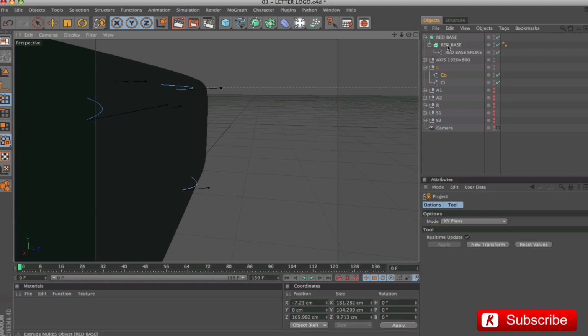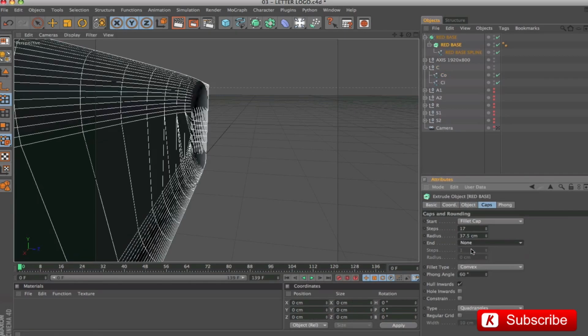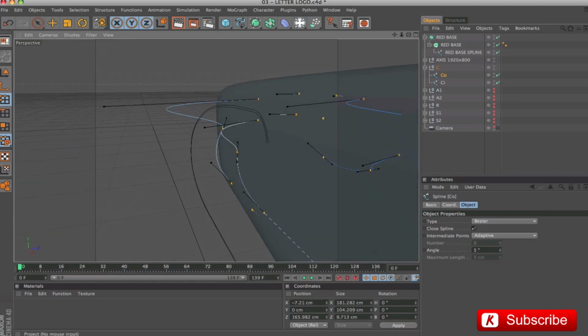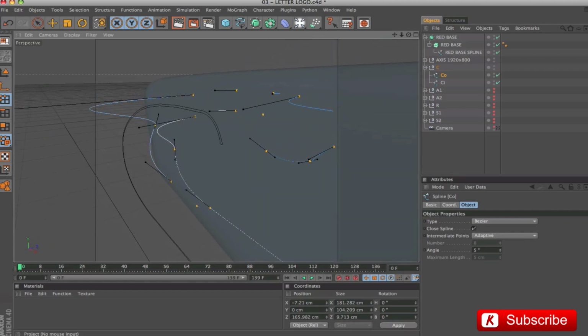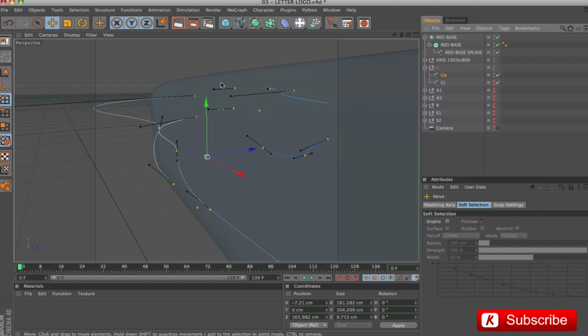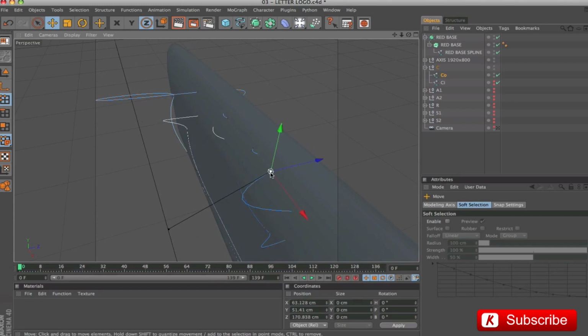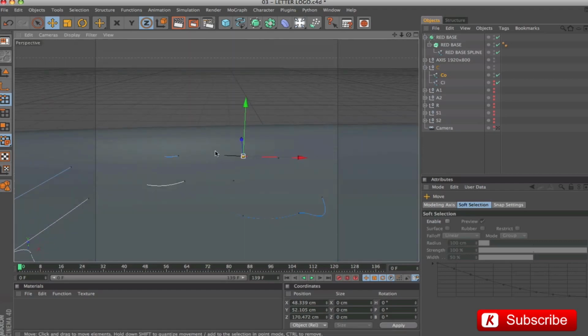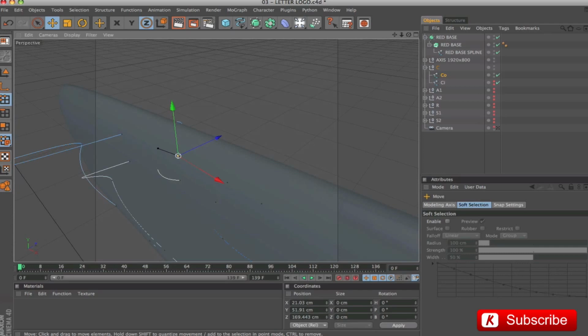To get a complete view of the back of the spline, we disable the fillet cap end on the red base. Activate the move tool so that it can move only along the Z-axis. This simple work must be done very carefully; when you see that the handles are arranged tangent to the surface of the red base, it is okay. Obviously check carefully that the move is correct. This work is not complex, but it should be done well to ensure a perfect adhesion of the round logo on the red base. It takes a couple of minutes.